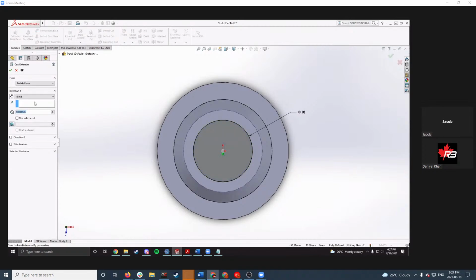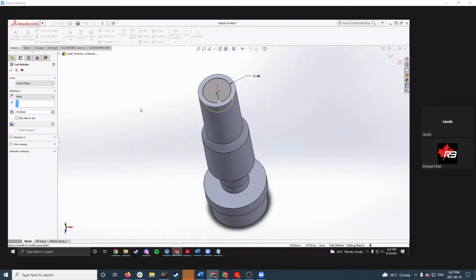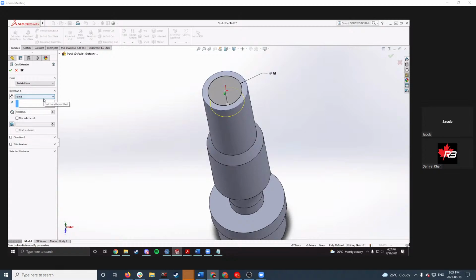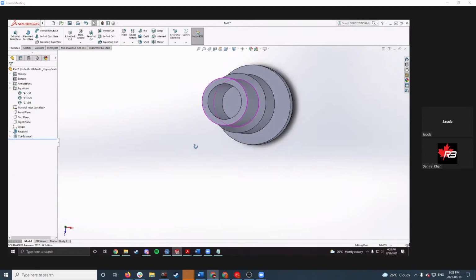And then I'm going to go blind. It's a blind hole and it's a depth of dimension C. So I'm going to go here, select this, and just type in equals C. You actually have to type in the quotation marks. That's important. I'm hitting enter right now and nothing's happening. So if I go here, quotation C, quotation, everything's good. Green check mark, blue color text, click check. And we have our blind hole.